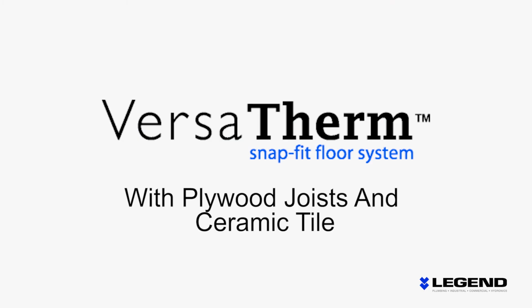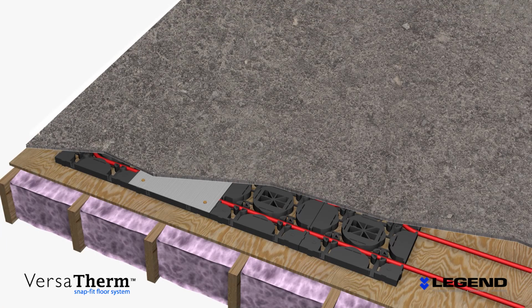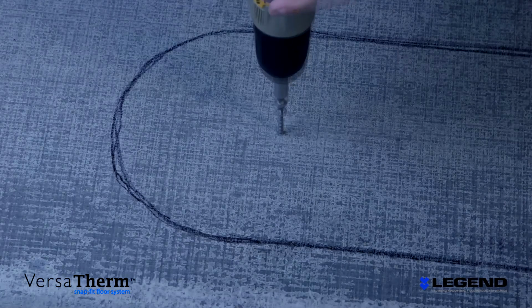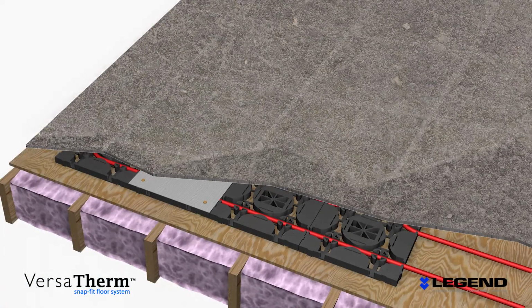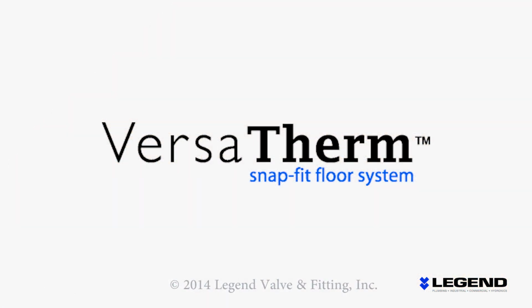When using VersaTherm with ceramic tile, the VersaTherm layer is sandwiched between the subfloor and the cement board, typically used for laying down ceramic tile. Be sure to mark where your tubing channels are before you start to screw down the cement board and VersaTherm layers. It is very important to stay clear of the tubing channels when selecting screwing locations so as not to damage the tubing. The cement board and VersaTherm layers are secured to the subfloor with 2-inch screws. Use a minimum of 6 screws per panel. It is recommended that you consult with the floor covering manufacturer and the installer for further guidelines. Once the layers are secured to the plywood subfloor, you are ready to lay down the ceramic tile floor. VersaTherm is designed to be just that simple and easy.